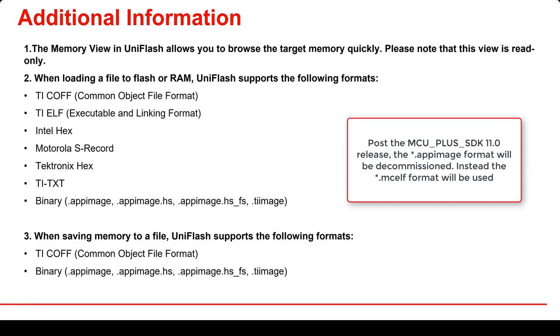Sometimes, if the flashing operation hangs in the serial session and the cancel button becomes unresponsive, please close the Uniflash tool, relaunch a new session, ensure the board configuration and flash configurations are correct, and try again.